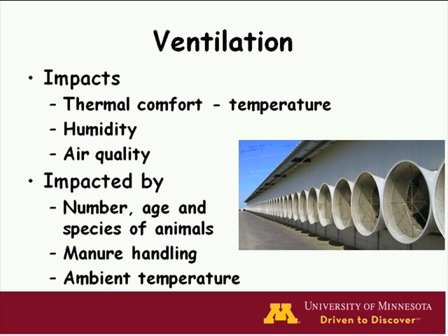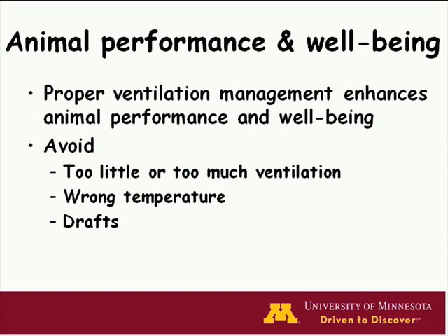It's clear then that ventilation does impact the thermal comfort of the animals and poults and birds that are in the barn, and it impacts the temperature and the humidity and the air quality. But sometimes it's not so clear that it's impacted by the number, age, and species of animals, and our colleagues will talk about that along the way. And manure management and handling is an important part of our ventilating systems, or it impacts it, and the air quality that they have in there, as well as the ambient temperature. We need to move more air in hot weather and can get by with less in cold weather.